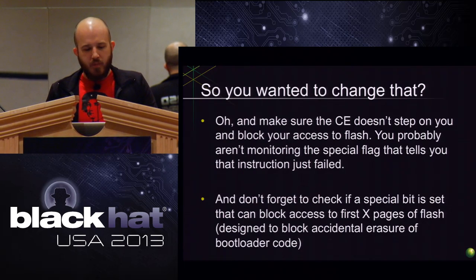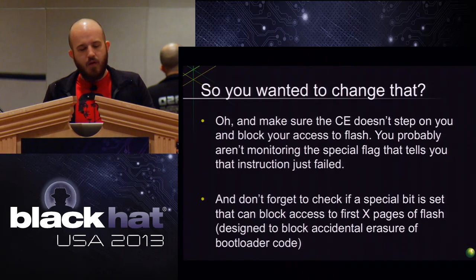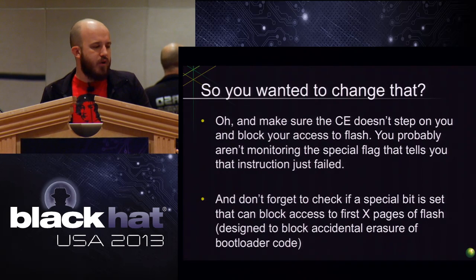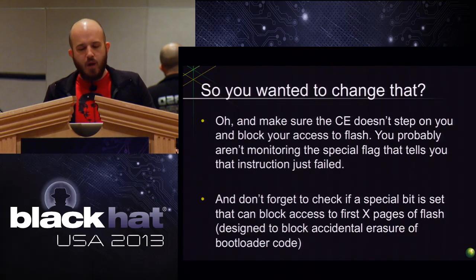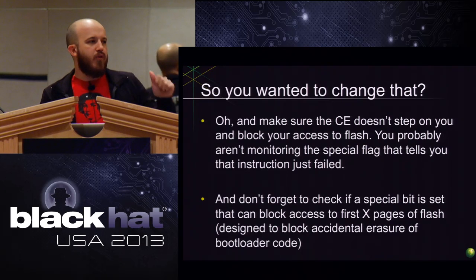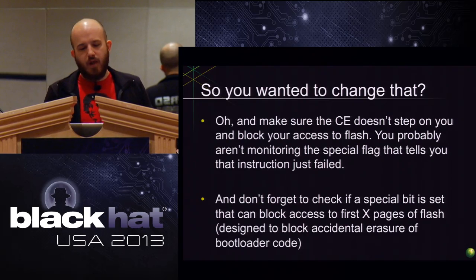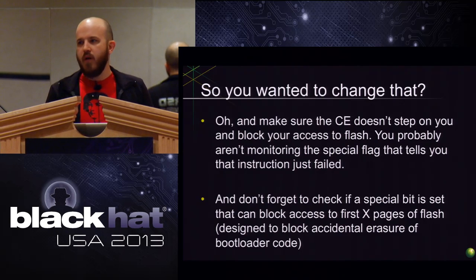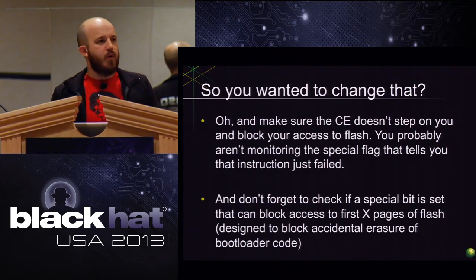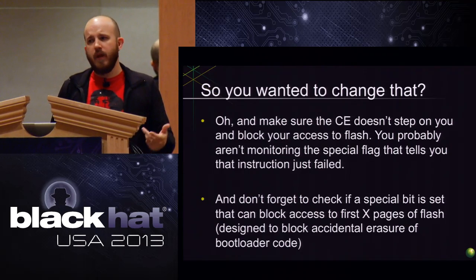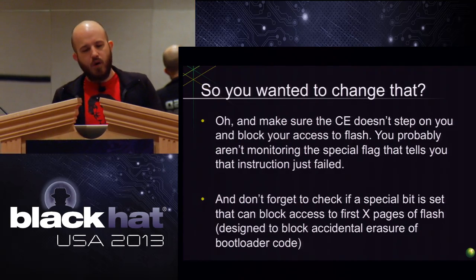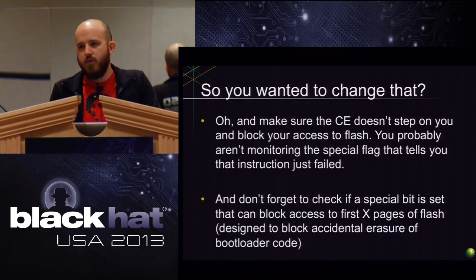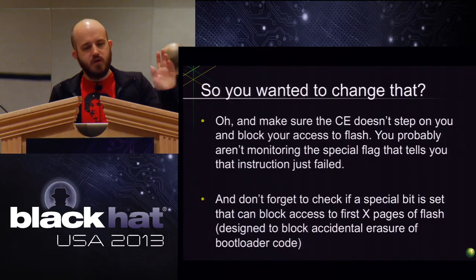Right, so the computation engine will step all over you. And then there's one other thing on here. It's not really a security feature. It's more just to make sure that certain sections of memory don't get overwritten. It has a way for you to set certain bits that say turn off the first X pages of flash from being able to be mass overwritten. So that would typically be where you would store boot code, for example. Something like a fail-safe, or the code that loads everything else. And so you put that there, and then you never want it to be overwritten. But it's just a bit, so there's no security feature to that. You can just go in and change it if you need to.